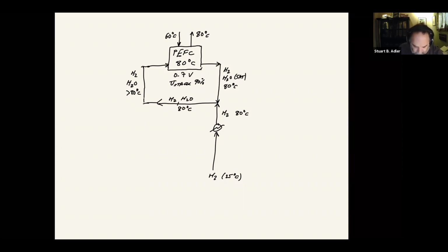And so if we think for a second, if we're using up moisture, we're pulling water from the anode compartment to the cathode compartment, we have to have an inlet of water someplace. And this is done by a variety of different methods. You can take gases and bubble them through liquids to humidify them. That's one way to introduce humidity into a gas. Another way is steam injection, where you have a boiler, you generate steam, and you just put the amount of gaseous H2O that you want into the process. I'm going to think about it that way for the moment.